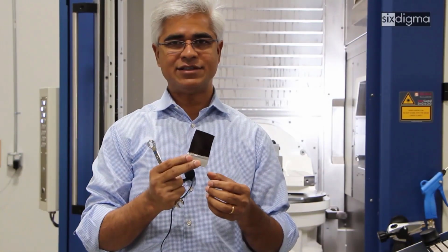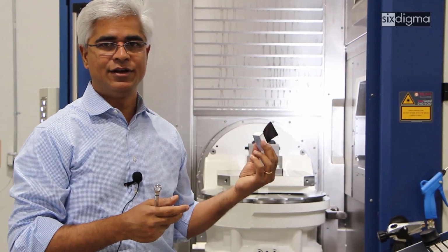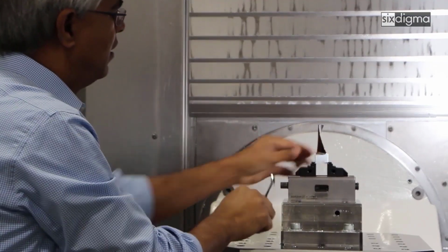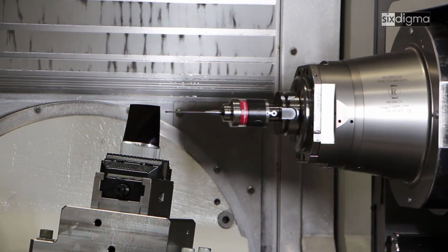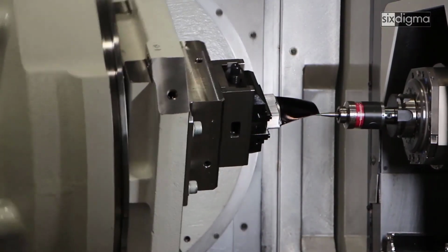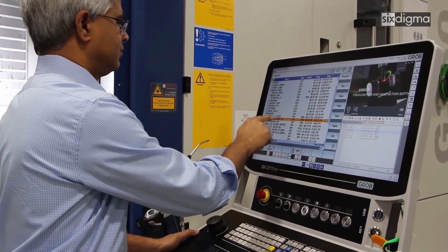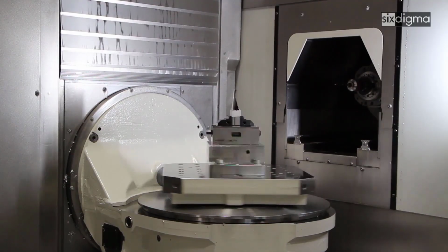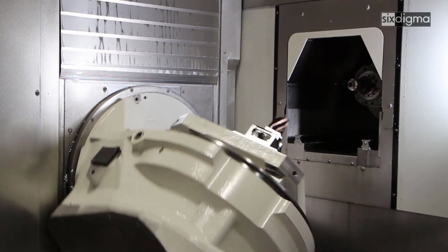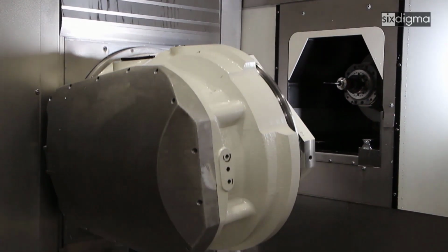Instead, we are going to place this part in a simple vise and use our Bloom Digilog scanning probe. This allows us to probe and push the probing results to the PCU on the controller, where we run our custom software. We compute the new alignment and mathematically assign the alignment to the fixture offset of this part.